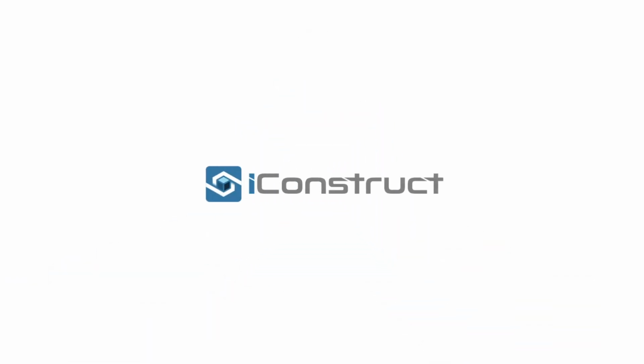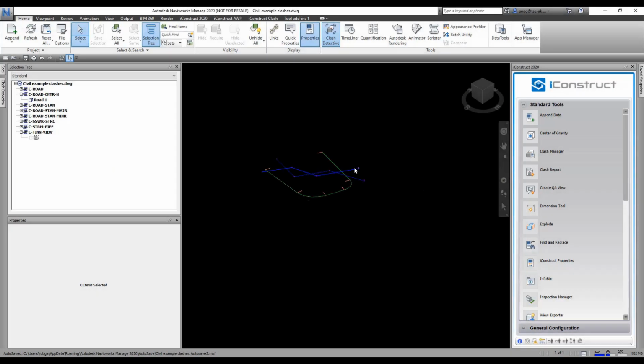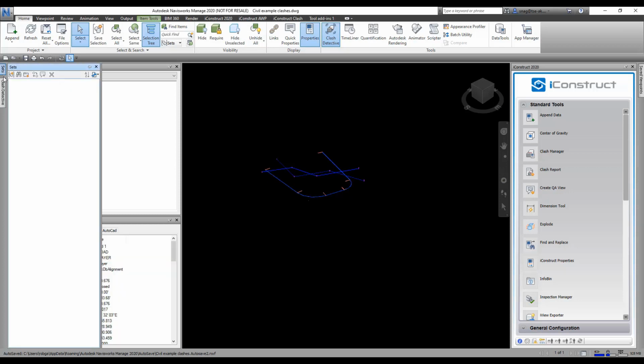In this short video, I'll be showing you how to group your clashes based on a station and an offset for civil projects. So in this model, I have an alignment and I have a storm sewer and a sanitary sewer. First thing I want to do is make sure I create a selection set of my alignment. So I grab my alignment on screen, come over here to sets, and I'm going to create a set. I'm just going to call it alignment.